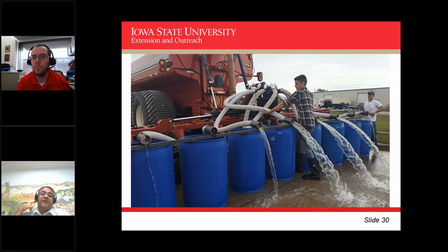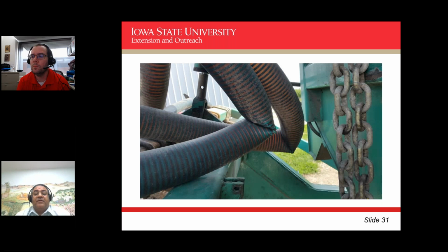So it almost becomes a point where the point will not discharge because the fluid cannot really flow in that particular line from the manifold. When you also have hoses that are crimped up in the toolbar like this, these are also practically plugged up.